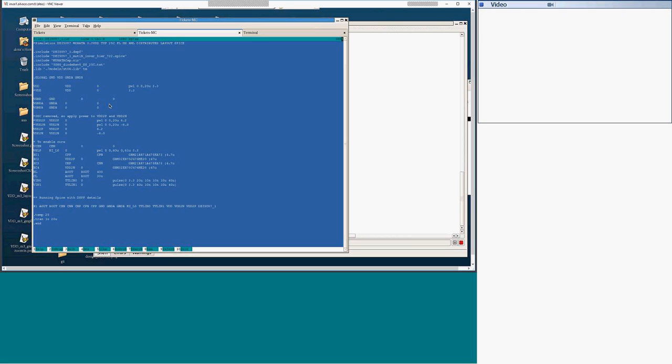Got it. Okay. Also, please make sure in the original netlist that Michelle gave me, there were quite complex subcircuits in the SPF netlist. We required that everything would be extracted to the devices or device subcircuits.